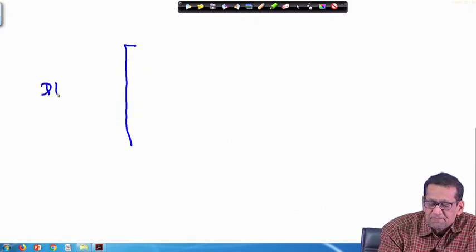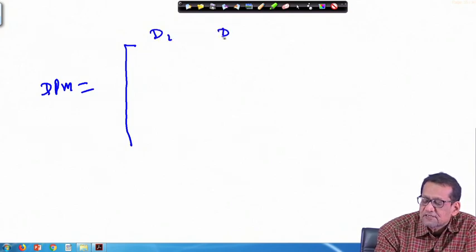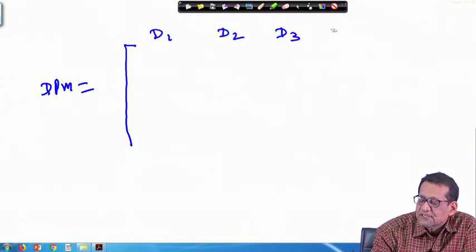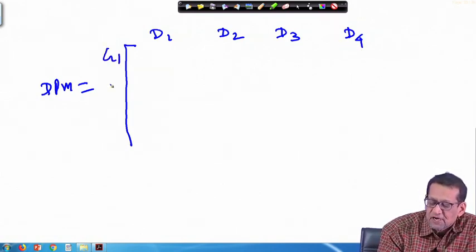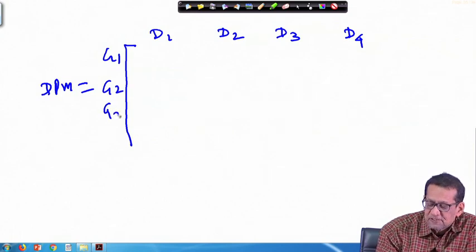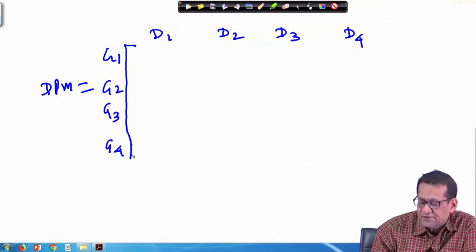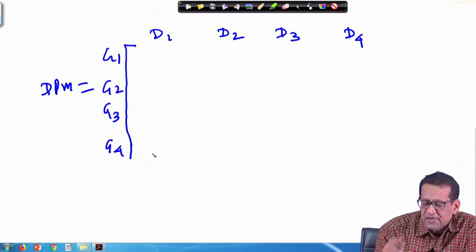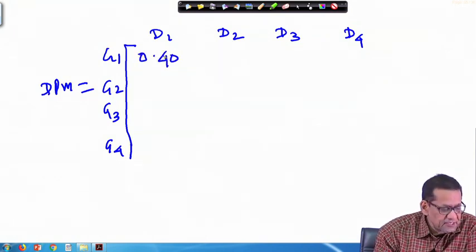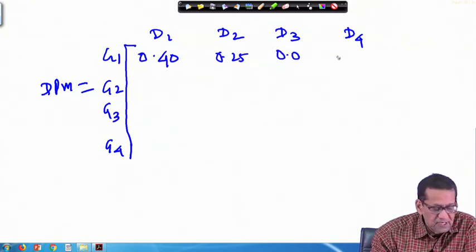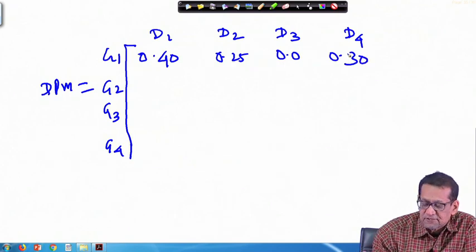So my DPM is equal to, say, this I will write D1, D2, D3, D4, that is DISCO 1, DISCO 2, DISCO 3 and DISCO 4, and this is my GENCO 1, G1, G2, G3 and G4, right. Next I will put whatever contract participation factors are given. So I will write here it was 0.40, right, then 0.25, then it was 0.0 and it was 0.30.